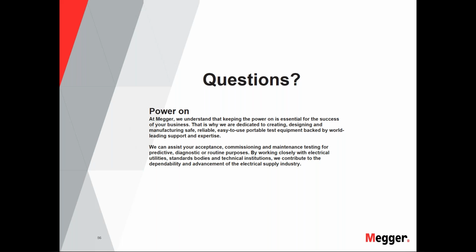One is during pre-commissioning, like the SEC test, where you can verify it. Or just inject the voltage from the HV side of the GSU, like a three-phase supply, and short circuit the secondary. You may see very little current generated, based on the reactance impedance of the generator and the stator circuits, but still you can see the current flowing into the circuit and check the CT polarities.